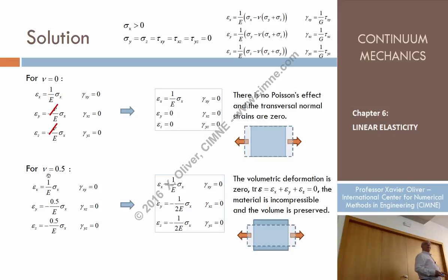And there are some of them. For instance, typically, what is the value of nu? Maybe you remember that, or you should remember that. You are structural engineers, you are engineers. What are the typical values of the Young modulus and the Poisson ratio for concrete and steel? Can you remember? In pascals or megapascals? 30 gigapascals. 30 gigapascals for the concrete.